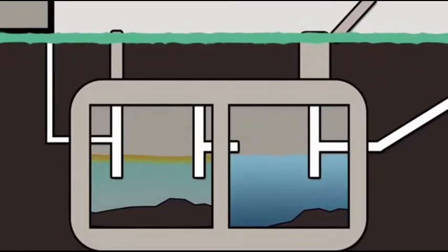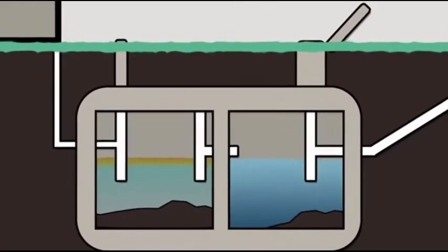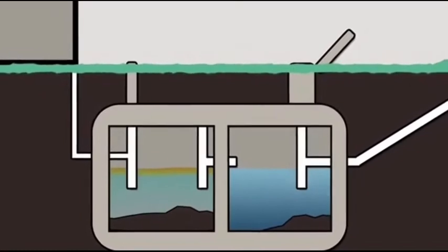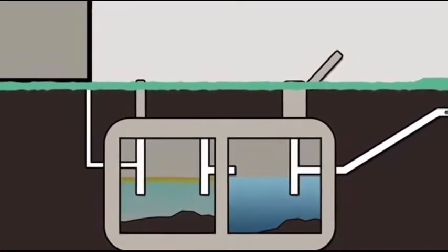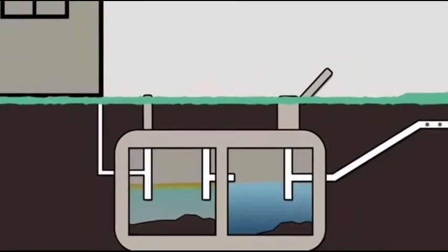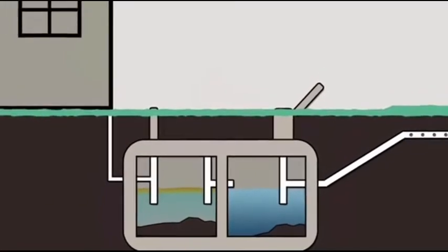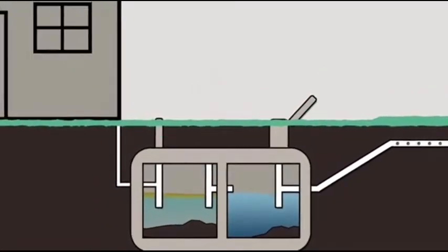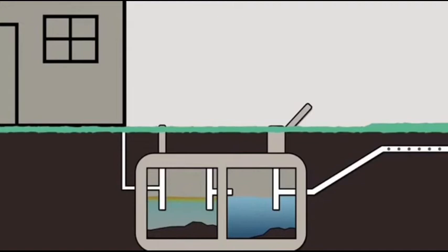When the holding tank is not pumped out frequently enough, the solids can enter the pipes leading to and from the tank. This can cause sewage to back up into the house or cause the drainage system to fail as the pipes and soil become congested.